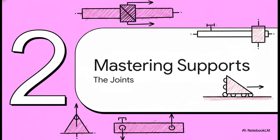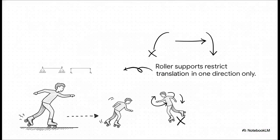Every single support we design in civil engineering is about stopping one or both of these specific movements. Which brings us to Section 2, Mastering Support Types, the Joints. You can think of supports as the actual joints of our structural anatomy. They connect the members to their surroundings, and they exert reactive forces to keep everything in its proper place. Take a look at this roller support. Notice how it restricts translation of the body along one direction only, straight up, perpendicular to the surface. But rotation? Totally allowed.